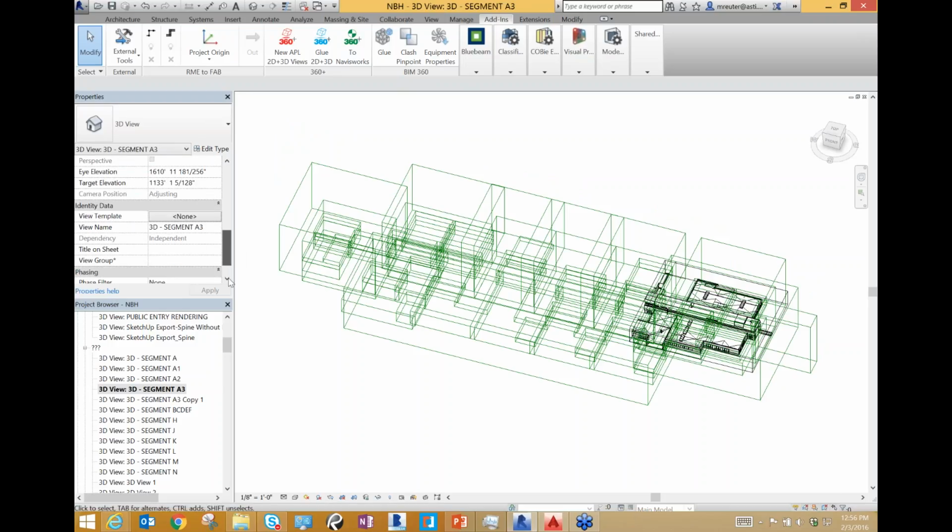scope boxes. And so basically, the architect, when he built this model, he created a whole bunch of views and scope boxes here so that he could basically create 3D views, floor plan views, maybe area plan views, maybe even sheets. These are really pretty easy to edit.